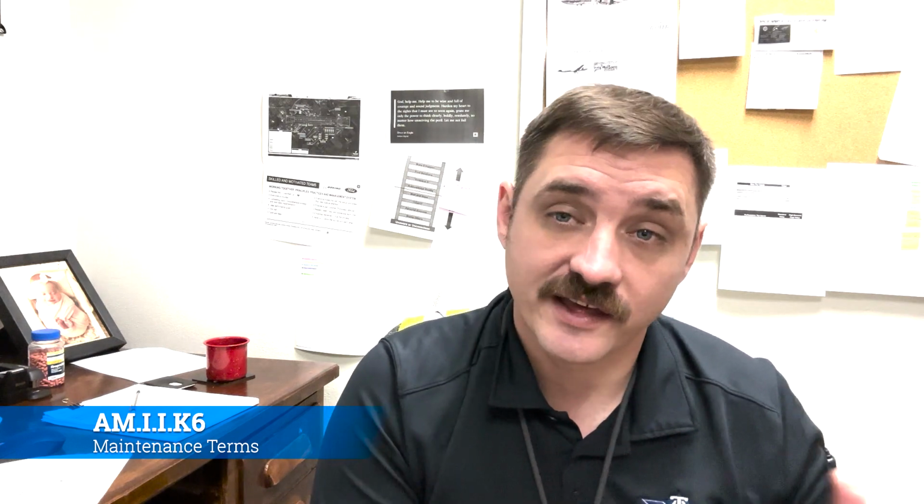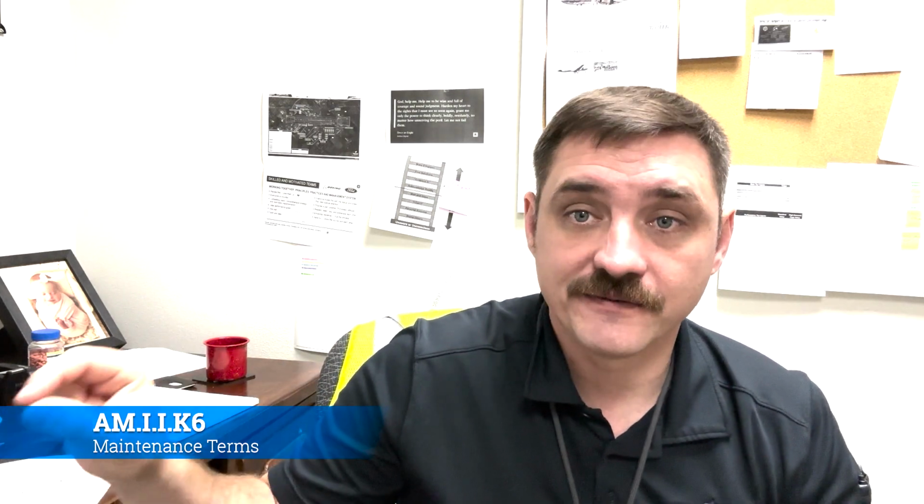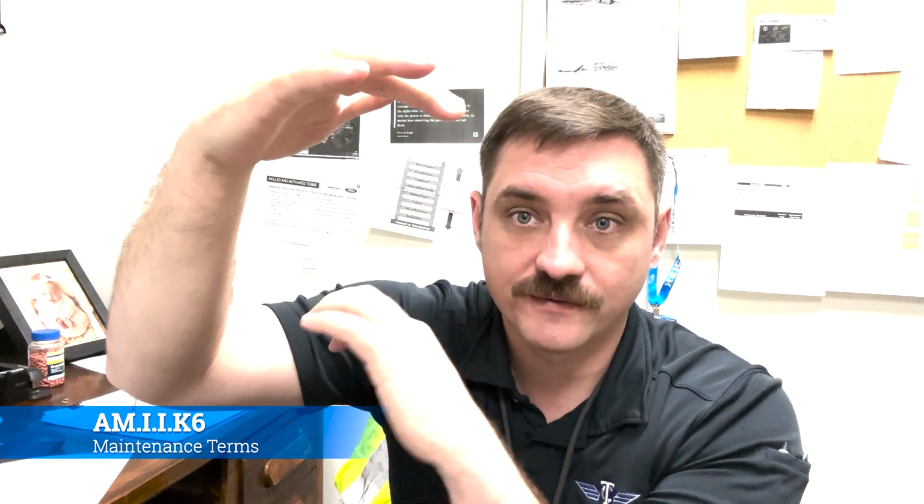I don't know that they don't have a 737 MAX, but let's say they only had 737 NGs. That MMEL applies to both Envoy's 737 NG and Alaska's 737 MAX. But Alaska will have a different MEL for specifically flying the MAX. You'll have the MMEL, the big umbrella for 737s, and then underneath you have, for Alaska's agreement with the FAA for their 737 MAX, just an MEL. So that is a little nuance that you'll want to know going forward.